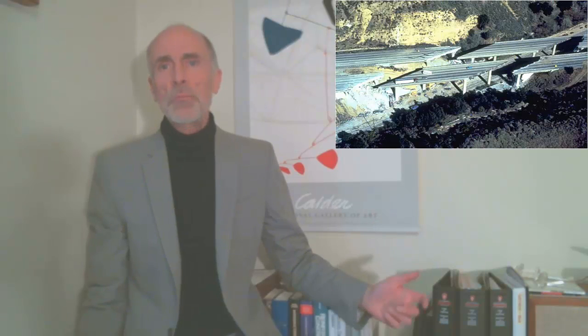Now let's consider how structural members and joints can be combined to create efficient structural systems. A structural system needs special combinations of joints and members to avoid problems. The 1989 Loma Prieta earthquake caused large enough displacements that a bridge fell off the support at one end. The same problem occurred in the San Fernando earthquake, when entire bridges fell off their supports. Supports are obviously important.